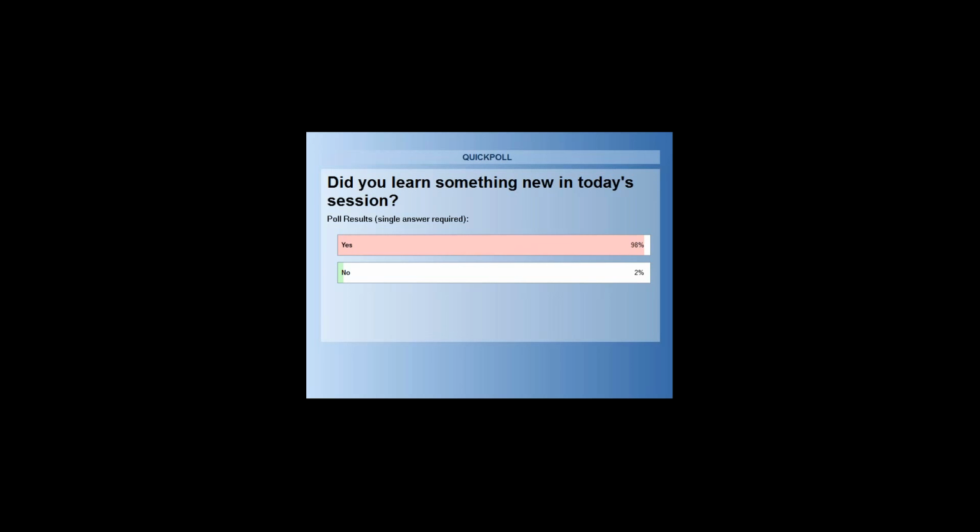I'm just guessing maybe, so the Express tools are just on the ribbon, right? I don't think they're available without the ribbon. So make sure the ribbon is enabled. Type in ribbon to make sure that's available. Actually, the menu bar system variable should show the Express tools. Yes, it does. Okay. Yeah, it just says Express though.